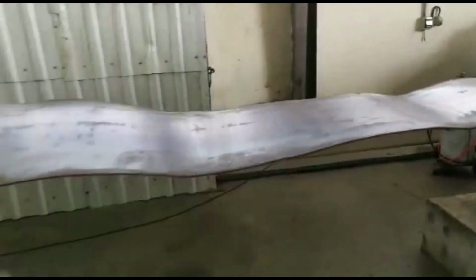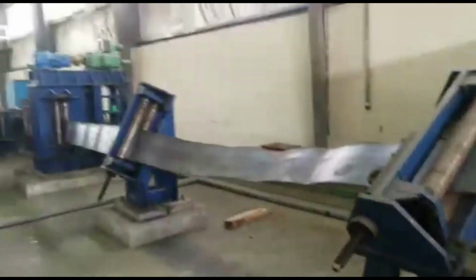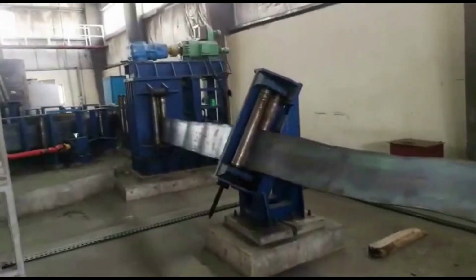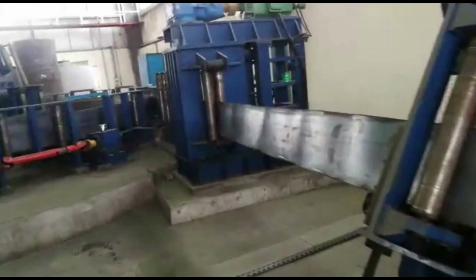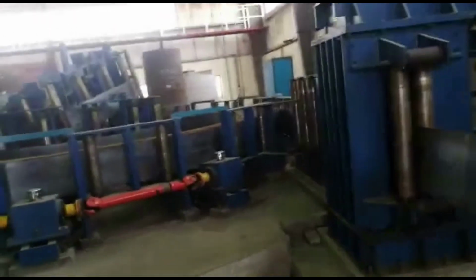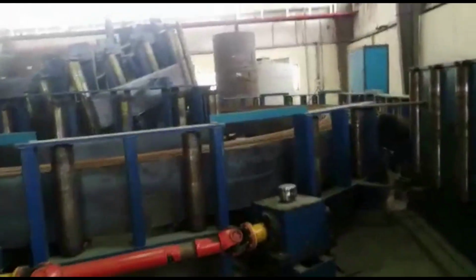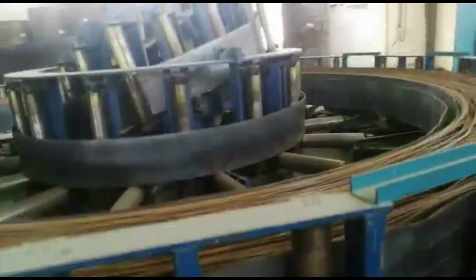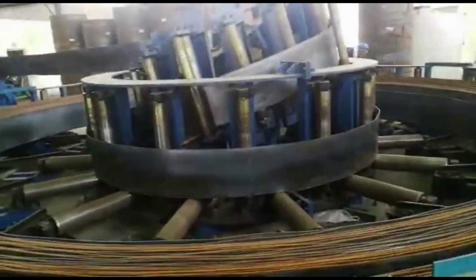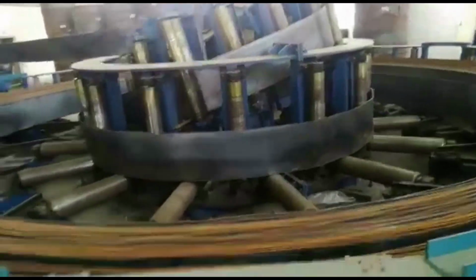Two accumulator overturning tables are provided to turn the flatbar, which is in horizontal position, into vertical position, and then it moves onto the accumulator. Whenever one coil finishes and another coil is fed in the uncoiler and welded, there is some time lag. Thus we would have to stop the process of pipe making each time a coil is uncoiled.